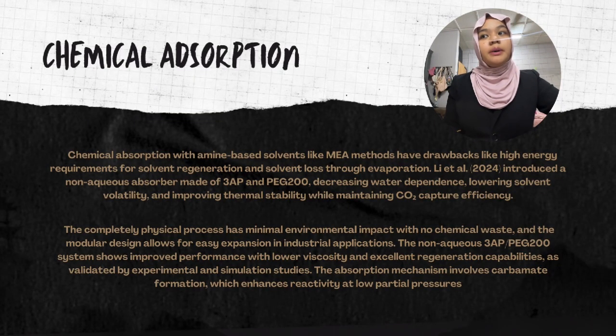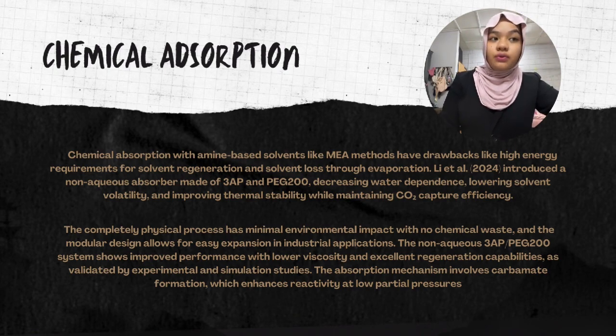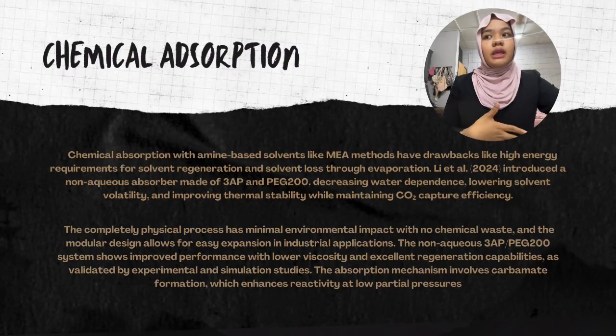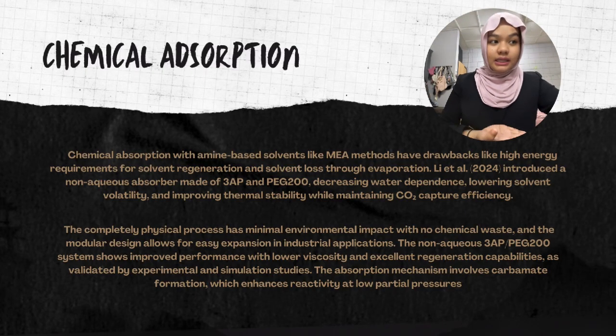Chemical absorption with amine-based solvents like the MEA method has drawbacks like high energy requirement for solvent regeneration and solvent loss through evaporation. Lee et al. in 2024 introduced a non-aqueous absorber made of 3AP and PEG200, which decreases water demand, lowers solvent volatility, and improves thermal stability while maintaining the CO2 capture efficiency.